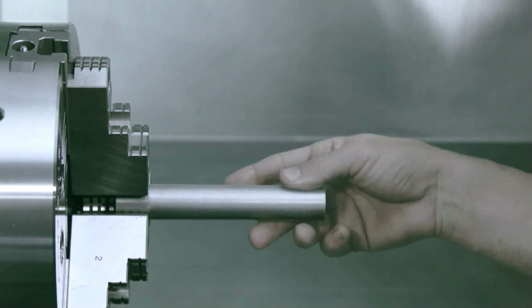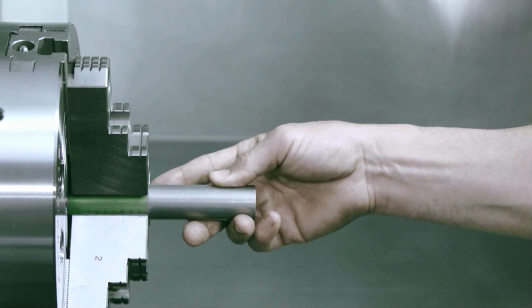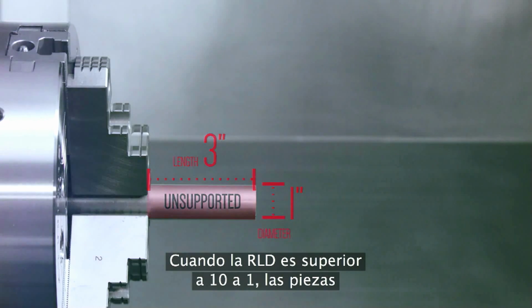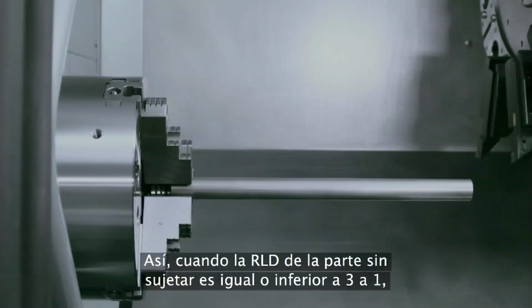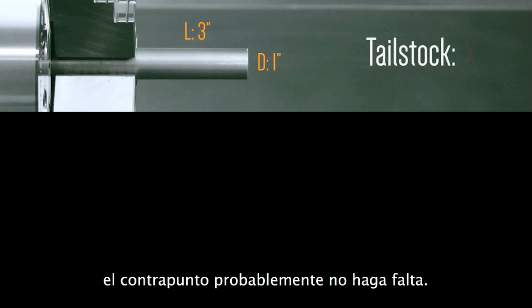However, the same 6:1 part, clamped with only 3 inches hanging out, will probably not need tailstock support, because now the unsupported region is only at a 3:1 ratio. Once you've exceeded an L to D ratio of 10:1, parts become so flexible that even tailstock support may not be enough.